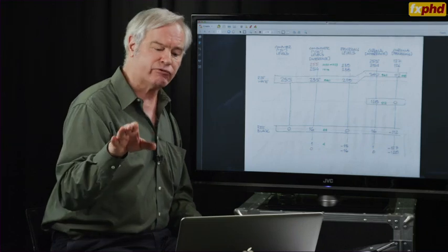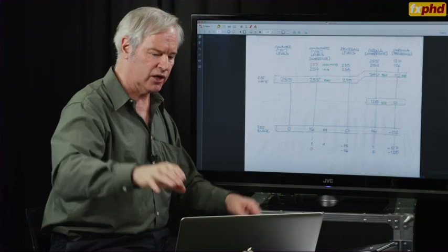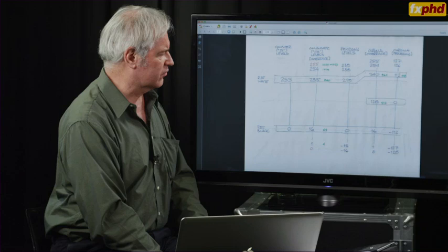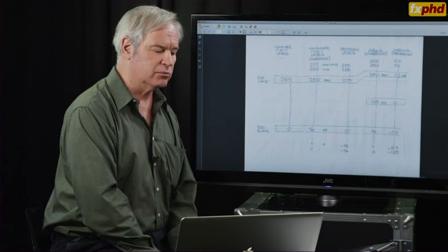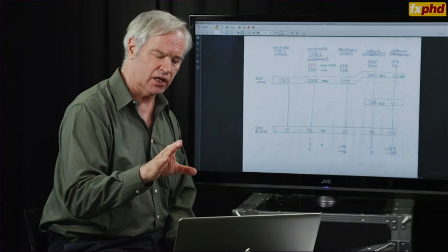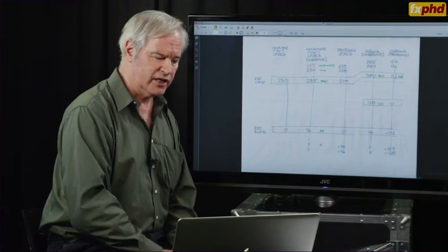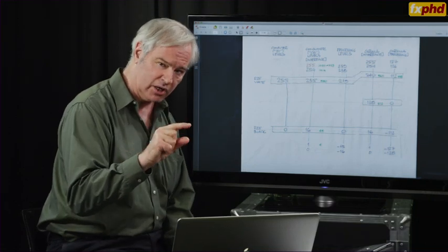And our preference for processing is just to subtract that. But there's a whole complicated story behind that, and that story is detailed in the book. Now, we will be headed towards YCbCr space, which is the standard space for representing studio digital video with a luma component and 2 chroma components.